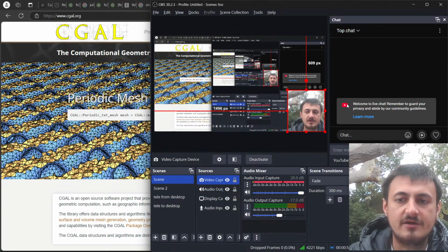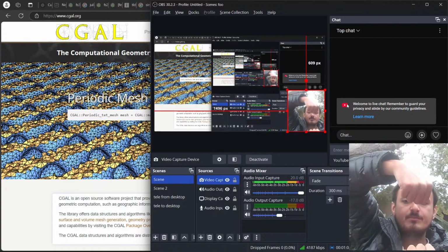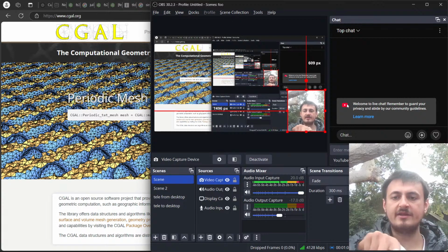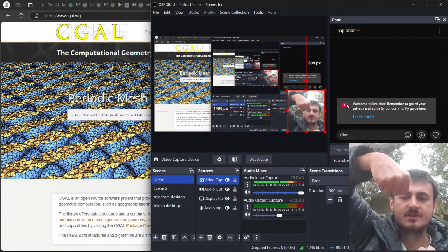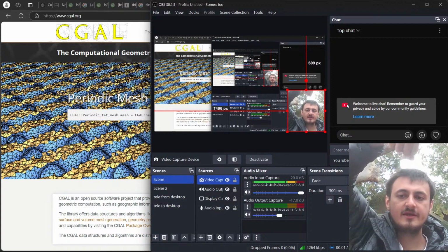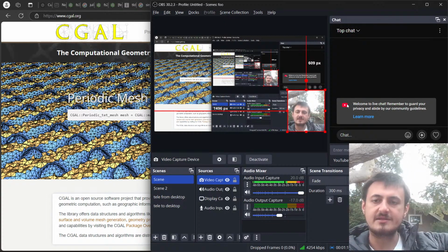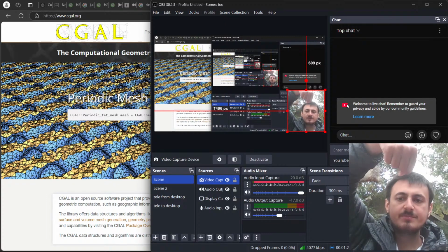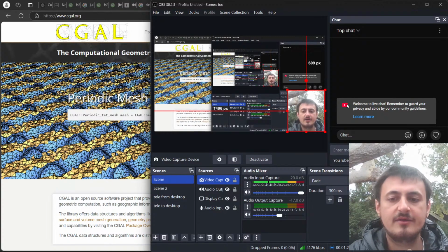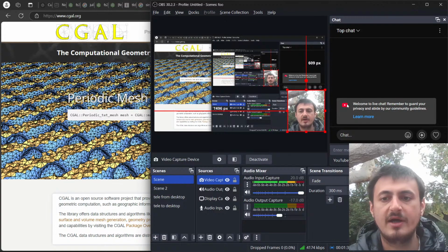So, anyways, the problems with finite element analysis on FDM parts is that first off, the layer lines. If a load is applied, let's say we have a hook, and I'm pulling the hook out like this, and the print orientation was perpendicular or parallel to the print. So let's say the layer defines a plane. The load is applied perpendicular to that. Then it will fail very differently than if you were to print it parallel to how the force is applied.